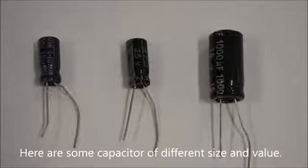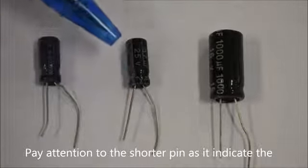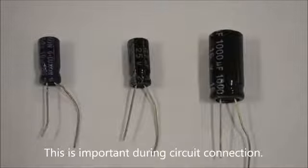Here are some capacitors of different sizes and value. Pay attention to the shorter pin as it indicates the negative side of a capacitor. This is important during circuit connection.